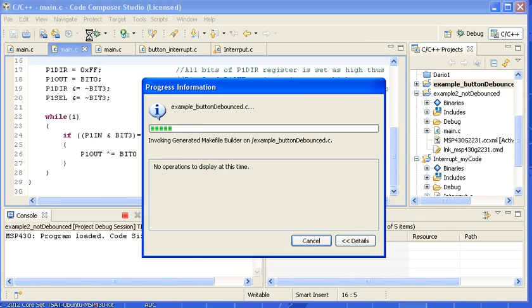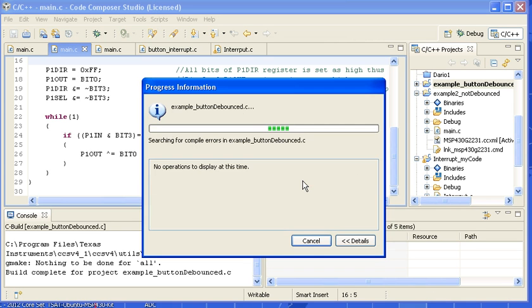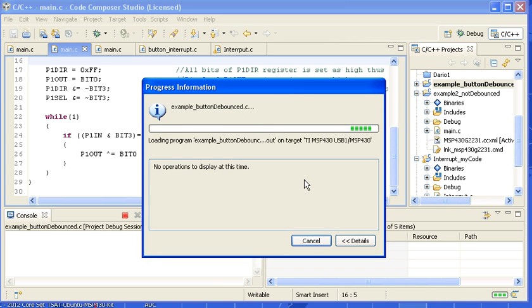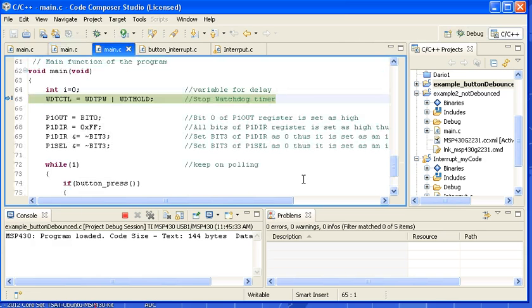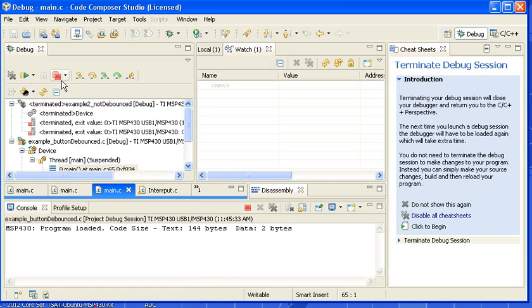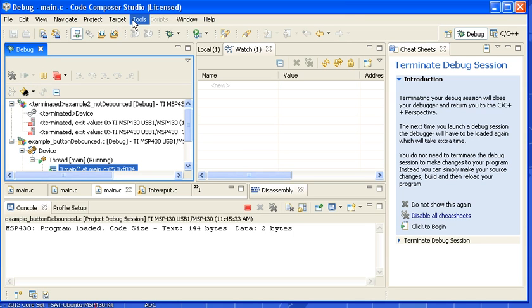So I compile the code, wait for a while. It is compiled, and yes, it does, I implement the code, LED turns on. So now if I press it, the LED turns on or off, and if I keep it held, you see the LED is blinking. So even though it is an improvement on the previous code, it's not quite what we want. We want the LED to turn on, and we want the LED to turn off. But if we press it holding, it will retain the previous state. It's not doing the work.